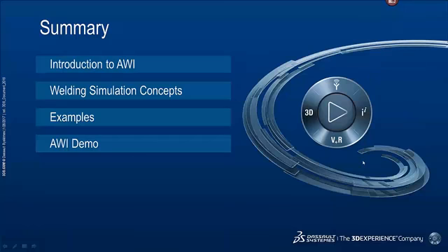I was going to say the work being done on the phase transformation will let you look at the heat affected zone. There'll be output variables that you can look at to see which materials have changed, and there's probably 20 different output variables in that work. But again, that's going to be a few more months before that's available. Yeah, with the phase transformation, of course, you get output variables for the fraction of different phases at a given time snapshot, many different variables you can contour plot.